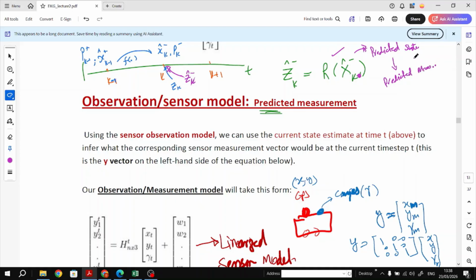Right. So then you take the difference between these two, the predicted state and the actual sensor measurements, and multiply with the Kalman gain at time k, and then add this term, not the previous, the predicted state, this one, and you update your state at time k like this.